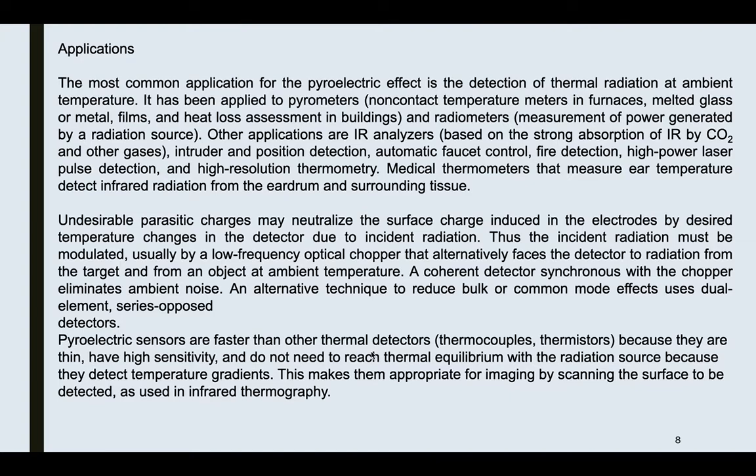Pyroelectric sensors are faster than other thermal detectors, thermocouples and thermistors, because they are thin, have high sensitivity, and do not need to reach thermal equilibrium with the radiation source, because they detect temperature gradients. This makes them appropriate for imaging by scanning the surface to be detected, as used in infrared thermography.